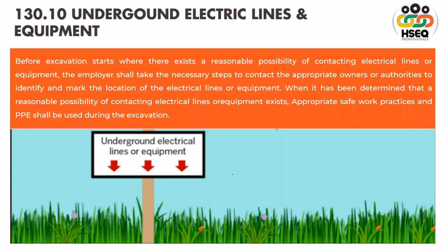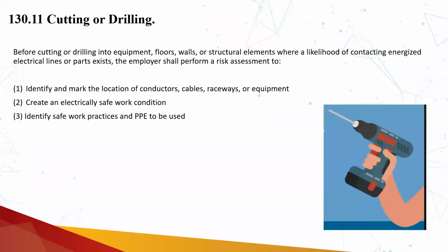And still if we are not sure, we can ask them to establish an electrically safe work condition for that particular area, so the excavation can be performed safely. Then 130.11, it's about the cutting and drilling into the walls.